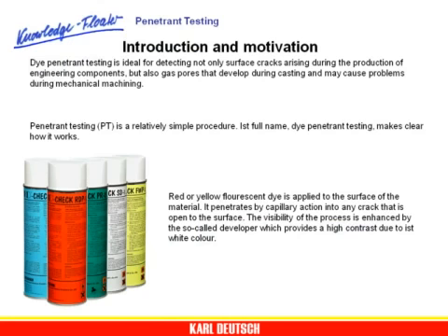Introduction and motivation. Dye penetrant testing is ideal for detecting not only surface cracks arising during the production of engineering components, but also gas pores that develop during casting and may cause problems during mechanical machining. Penetrant testing is a relatively simple procedure. Its full name, dye penetrant testing, makes clear how it works.